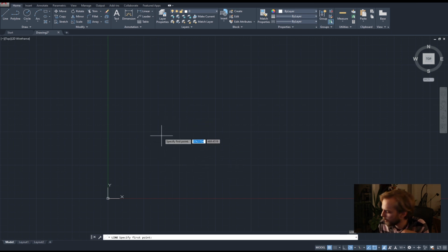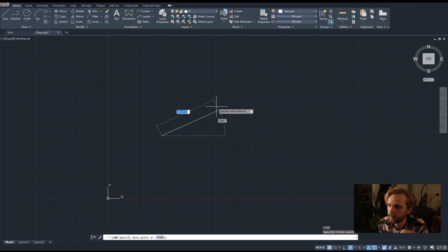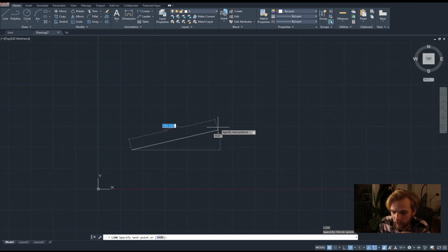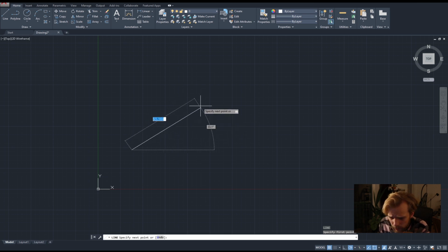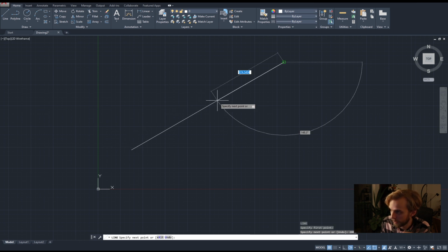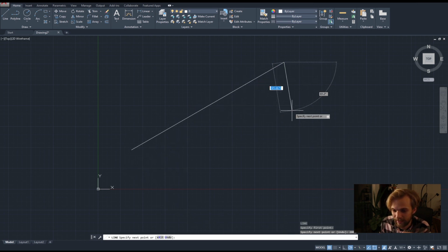I will specify the first point by just clicking, but then the second point, let's say I want it at this angle, whatever angle, but I want it to be, let's say, 2 meters long, 2000 millimeters. So before I click again to finish the line, I can type in the desired length, 2000, 2 meters, enter. And now it becomes exactly 2 meters long in that direction, right?